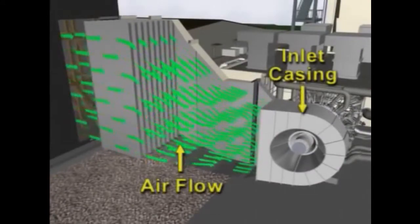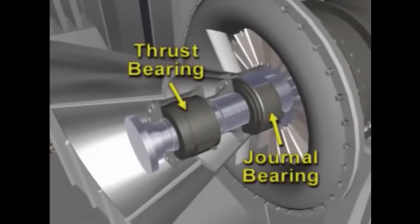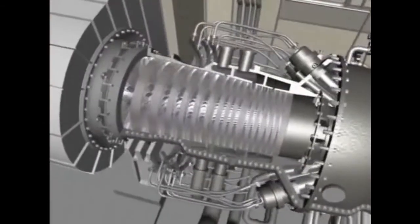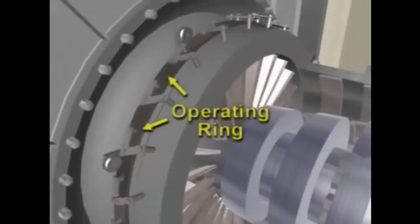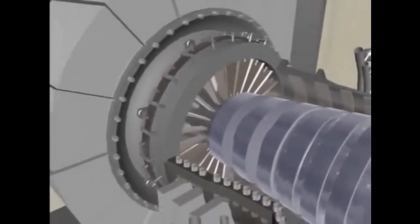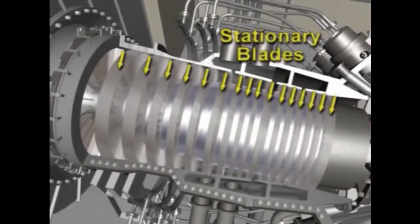The inlet casing provides a smooth transition flow of air from the filters, through the silencers, and into the axial compressor. The inlet casing also provides access to the thrust bearing and the inlet journal bearing. Variable inlet guide vanes are located in the inlet casing directly in front of the first row of compressor blades. The vanes are used to regulate the amount of air entering the compressor. The circular operating ring actuates the guide vanes so that all vanes move in unison when opening or closing. Before each set of rotating blades is a set of stationary blades, or blade rings, that direct the air to the next set of rotating blades.